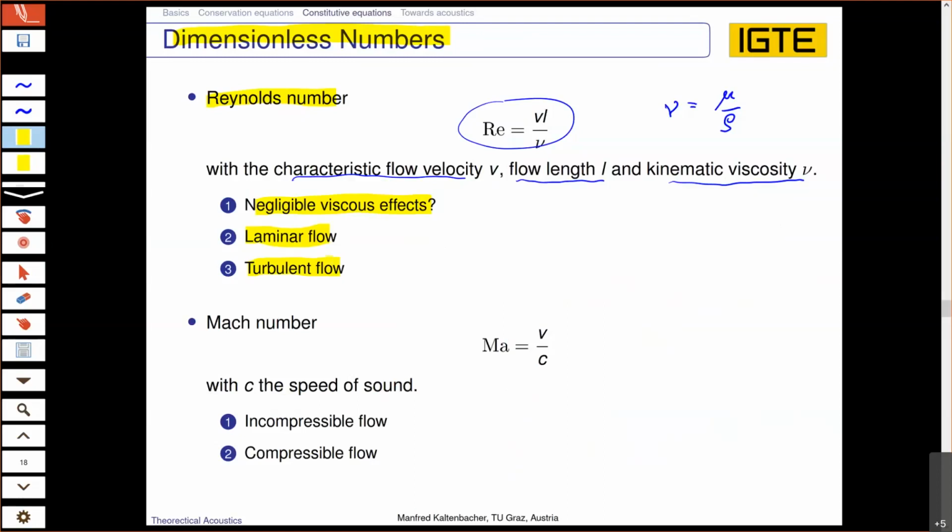Exactly. And then you have to imagine when we look, for example, at really turbulent flows, you have Reynolds numbers up to 1 million or even higher. And then the big challenge is how to resolve all these turbulent scales when you numerically solve the compressible flow equations. Almost impossible. But that is very important and gives us some idea how we can perhaps simplify our mathematical equations to model our specific case. So that's the Reynolds number.